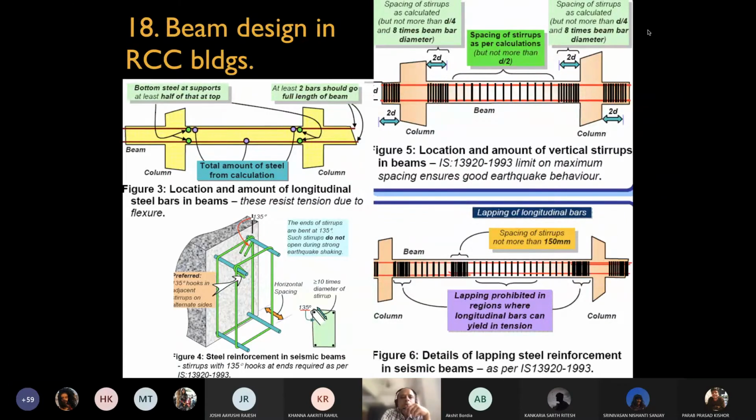This slide shows how things have changed over time, even for the stirrups in the beams. In earlier times, they were all evenly spaced. It was only about shrinkage cracks. Now these stirrups are put in place not only to avoid shrinkage cracks, but also to take into consideration that at the corners there will be shear cracks.